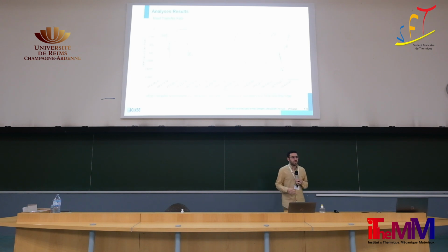In this graph, we are showing the heat transfer rate. As you can see, the values are negative because it's cooling, and we are considering that the heat transfer is out of the system. You can also see that we have some zero values of this heat transfer. This is because of bypass, because the system was not functioning during the hours where the ambient air temperature is lower than the soil temperature, and this mainly happens during the night, so the system is not functioning during these hours. We can see in this graph that the maximum heat transfer rate can reach up to 1,188 watts, and during the whole week we can retrieve about 65 kilowatt hours of energy using this system.